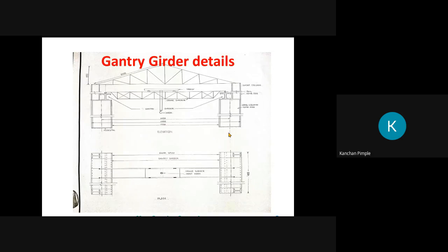But as per our discussion in sheet number 5, you have to draw all dimensions in mm. So instead of 17.5 meter, here you have to write 17500, and no need to write mm, as in the sheet we already write that all dimensions are in mm. So this is 17500, overall 17300.